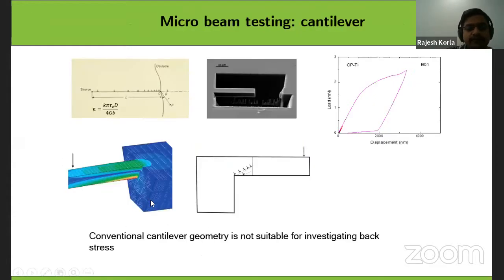And then we also did, in Oxford, this is basically a commercial titanium pillar. Basically, what is the advantage? What we want to study is that when you apply a load, you develop tensile stresses here. These tensile stresses create dislocations, and you put a grain boundary here. All these tensile stresses are going to interact with the grain boundary. That is one of the objectives of what we have done on this sample.